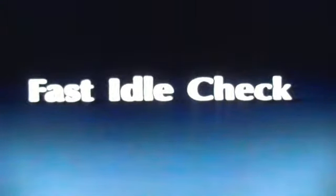The next thing we want to do is set the fast idle. This is important because the throttle position sensor is adjusted on the high step of the fast idle cam, and we can't get an accurate TPS adjustment without the fast idle being properly adjusted.